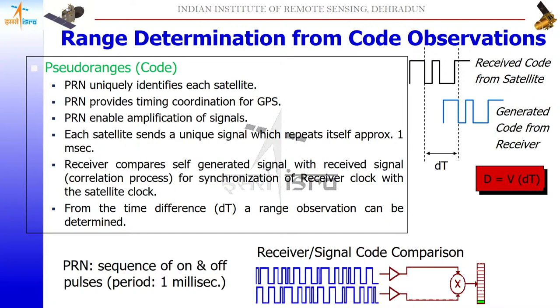And if we have a 24-hour observation, or 2 days, 5 days of observation at a 15-second sampling interval, we can have very precise information. Then we can resolve all the ambiguities and estimate a precise dt. Once we have a precise dt, we can get the precise true range. The pseudo range can be the true range, meaning velocity into dt.